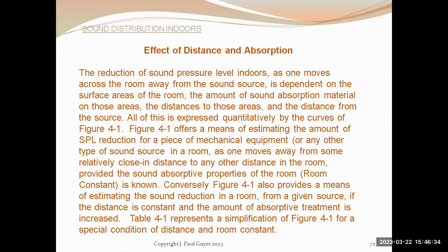And so the building materials that you select, every building material has different acoustic characteristics at different frequencies. So you need to be aware of the frequencies that are being produced in the source room, and then select the building materials that have the highest absorption at that frequency.